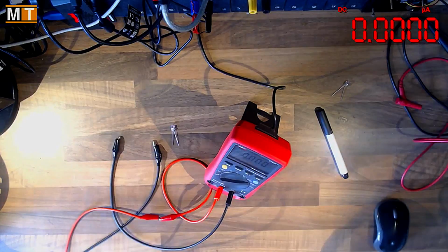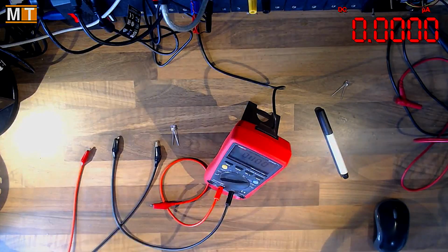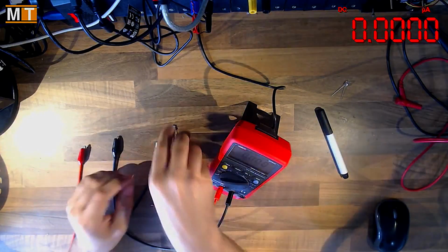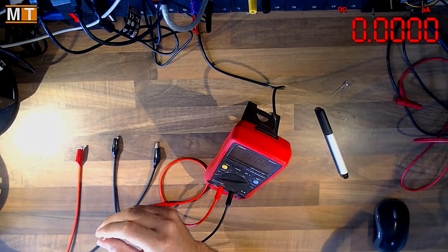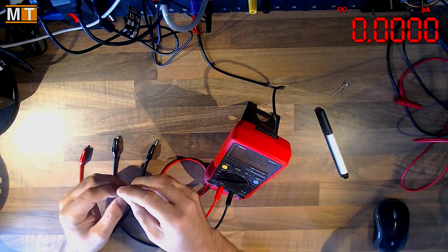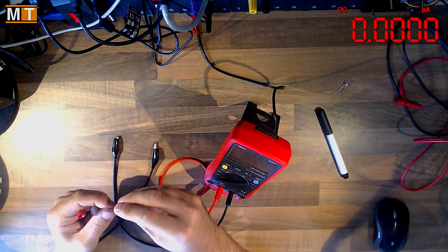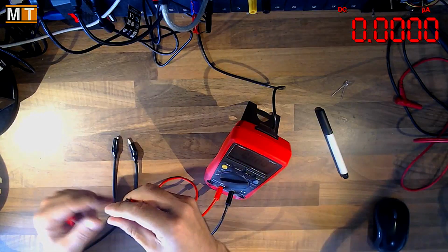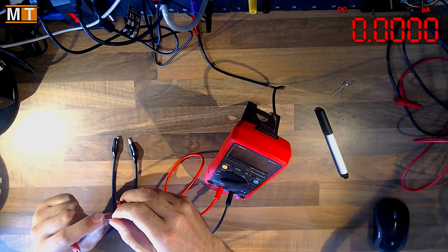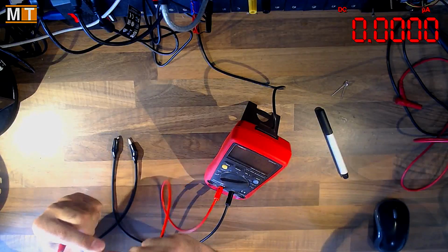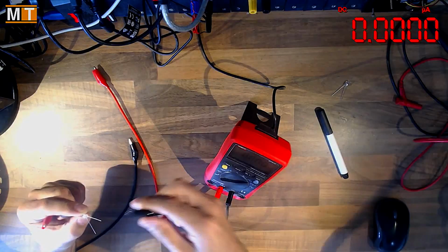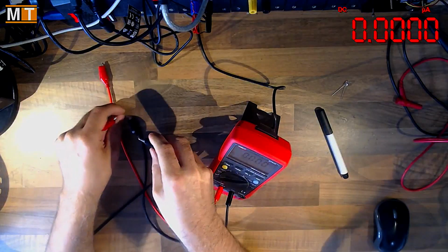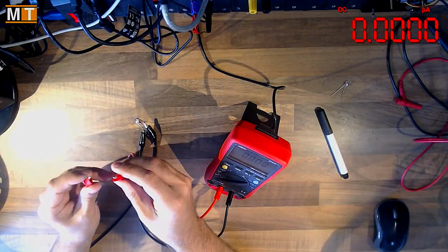Okay, so why a resistor? Very simply, to stop any of that happening. We need to provide about 2 volts to this LED. We have 5 volts and we have an unknown current limit, 1 amp. At 5 volts, 1 amp, I shall feed this through my DMM at amps. Where's the flat side? There's the flat side. That's coming out of the DMM. That's going to ground. Okay, 5 volts, 1 amp.